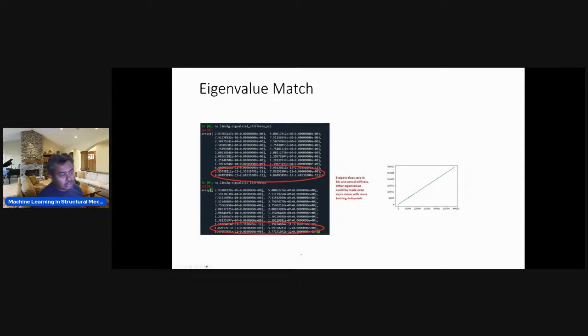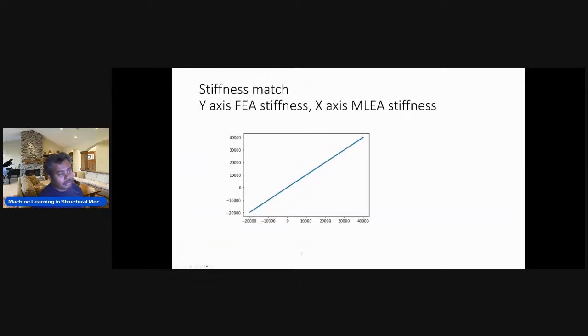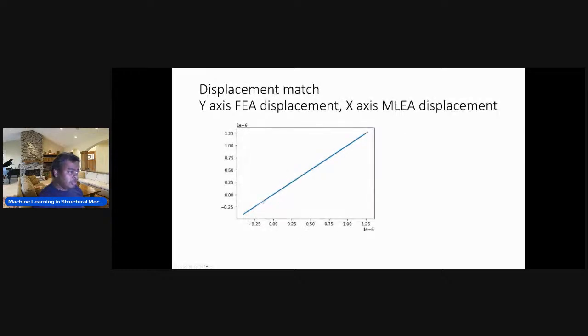So in a nutshell, I would like to go through the results again. There is a good match between the finite element counterpart and its machine learning counterpart in terms of the actual stiffness components, those 300 components we were talking about in the upper triangular matrix. This is followed by the displacements. They match if you put a certain type of boundary conditions. The displacements obtained through the finite element method and through the machine learning element method are one and the same, and this could be repeated for other types of boundary conditions, so to speak.